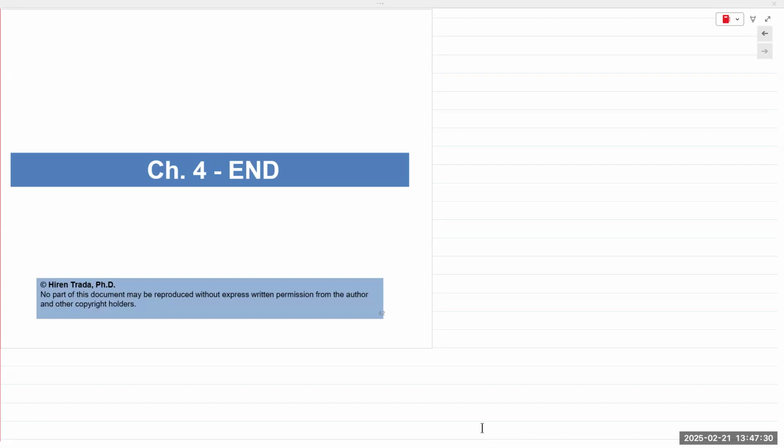So again, we use the NAND gates to create your flip-flop, so that's procedure 1. And then procedure 2 is creating a 4-bit counter, the one that we just talked about. Output of each is fed as clock to the next one. That's the ripple counter that we saw last class, right? When you build this circuit in the lab, you're going to use 2 chips, 74107 and a second one, 107. So that's the first, and that's the second.